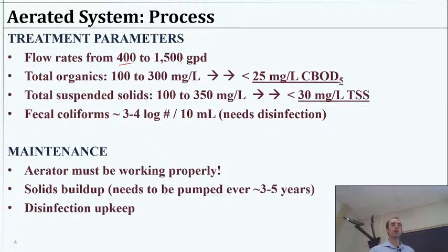Yeah. And one of the things about these flow rates, by the way, is because we were kind of scheming a design, this would usually be all happening in about 6 hours. So you don't really have much of a flow rate at 3 in the morning, typically. Maybe an occasional flush, somebody gets up to go to the bathroom, right? But in general, your flow rate is very low for a lot of the day.